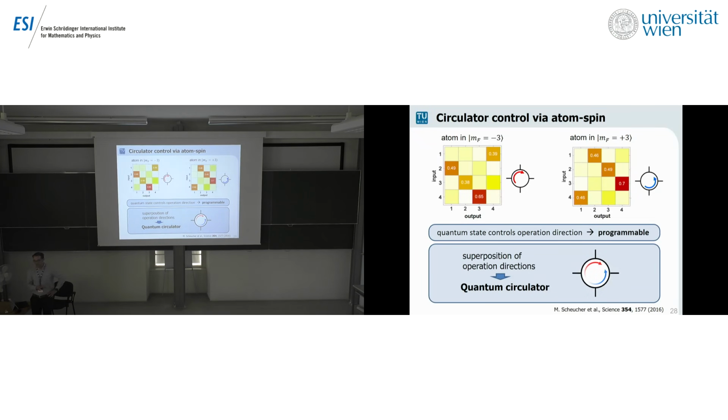At the moment, the main limiting factor is the quality factor of our resonator. In order to make efficient coupling between those two fibers, you ideally want to couple both of these fibers critically, meaning that they balance with the losses of the resonator itself, the coupling rates. And this can only be reached when the intrinsic losses are 0.